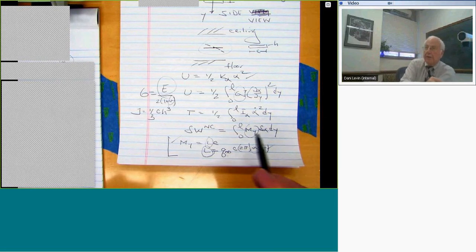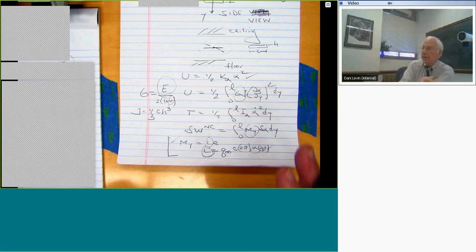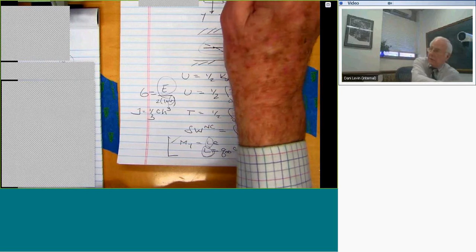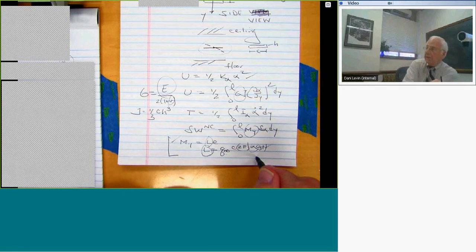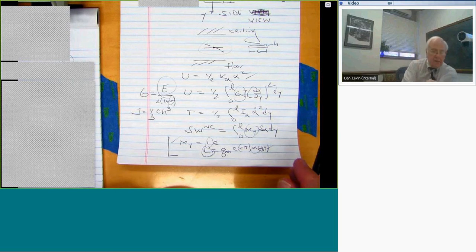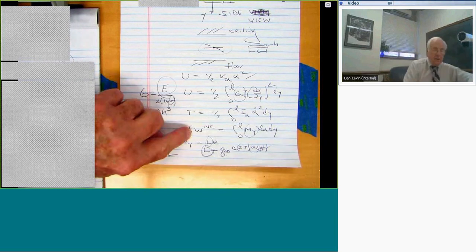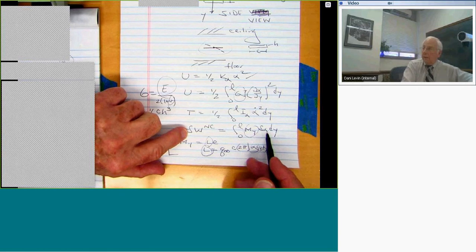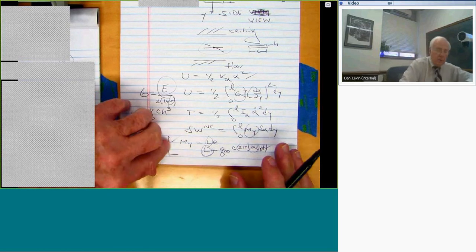There's what is called an aerodynamic induction effect. That is, the twist over here changes the lift over here. This model does not allow for that. So that's one thing. Another thing is, an even better approximation is not to represent this in terms of moment and alpha, but to represent it in the following way.